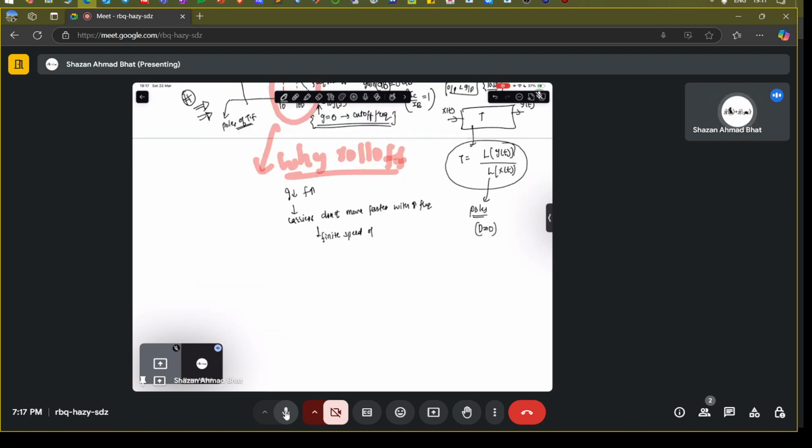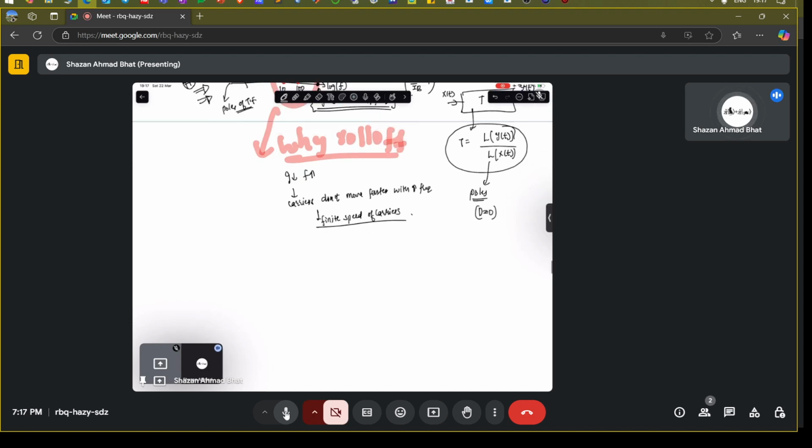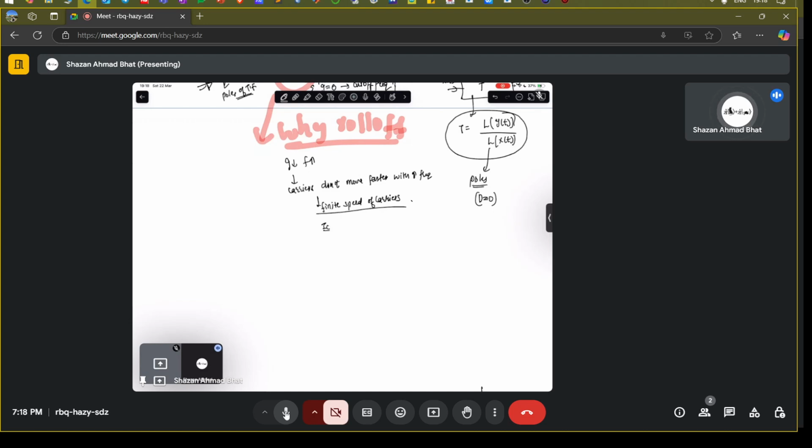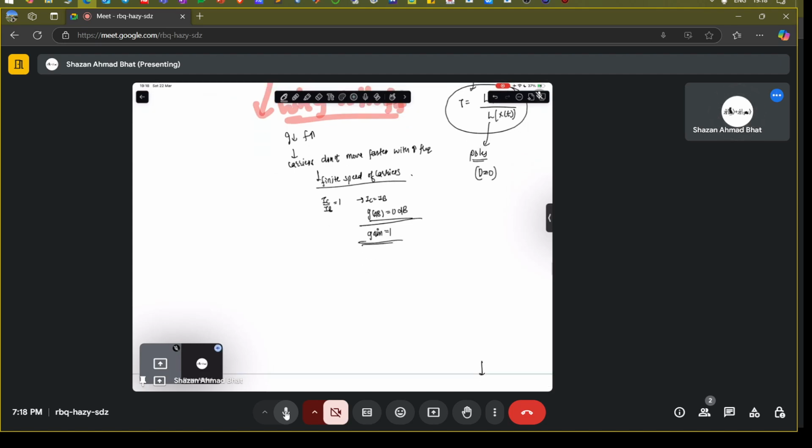Here we are talking about the base region, or in the MOSFET, the channel. So eventually IC divided by IB becomes equivalent to 1, or IC becomes equivalent to IB. So you have the gain equivalent to 0 dB in the decibel scale, or the gain becomes equivalent to 1 in the linear scale. That happens when F is equivalent to FT, which is the unity gain frequency. That is the fundamental concept of it.